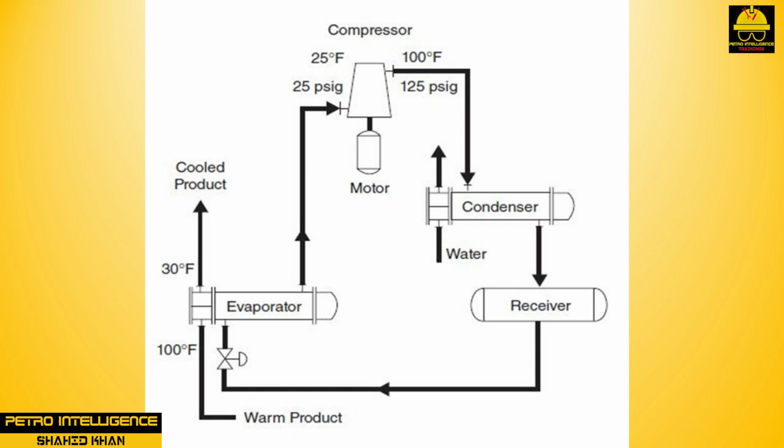It is a good design practice, because of safety considerations, to operate the first or lowest stage compressor suction at a positive pressure to establish the minimum operating temperature. The other temperature levels are set by the design of the particular system.